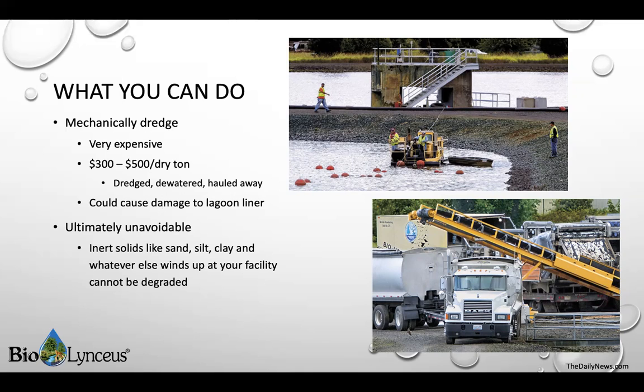Mechanical dredging is ultimately unavoidable. Even with adequate biodegradation of sludge, inert solids like sand, silt, clay, and trash cannot be degraded. These inorganic solids will slowly accumulate and will need to be occasionally dredged.